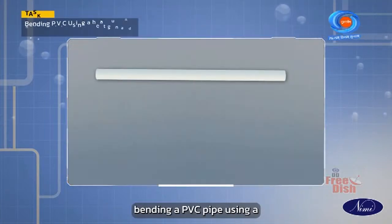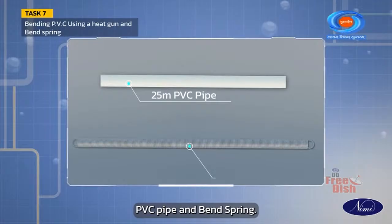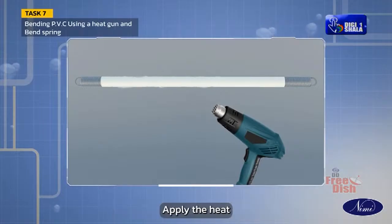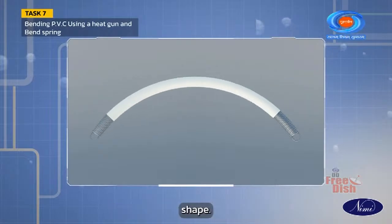Bending a PVC pipe using a heat gun and bend spring. Take a 25 mm PVC pipe and bend spring. Insert the bend spring into the pipe. Apply the heat evenly around your planned bend. Slowly bend the pipe to the planned shape.